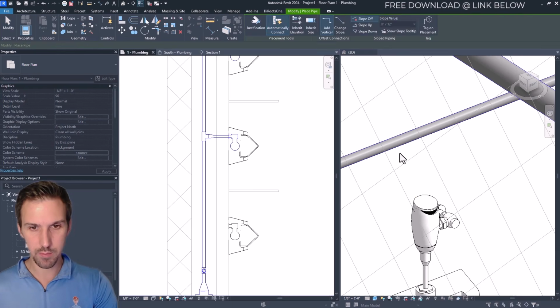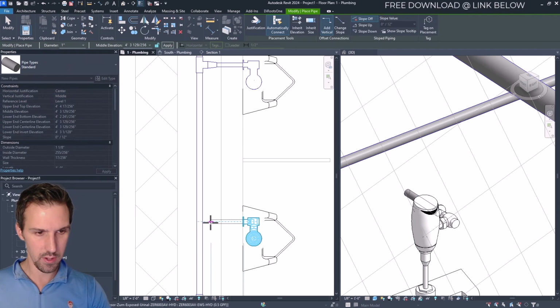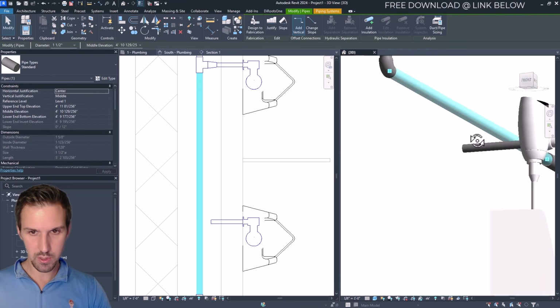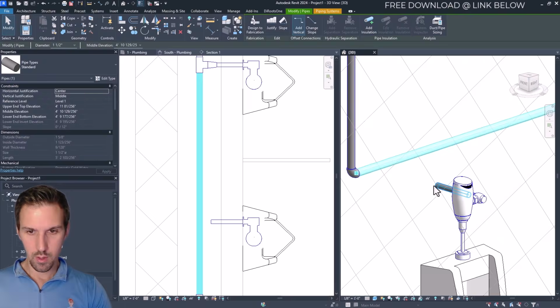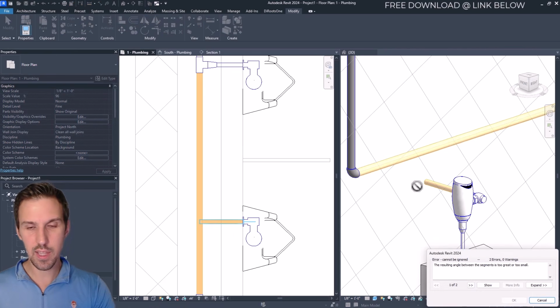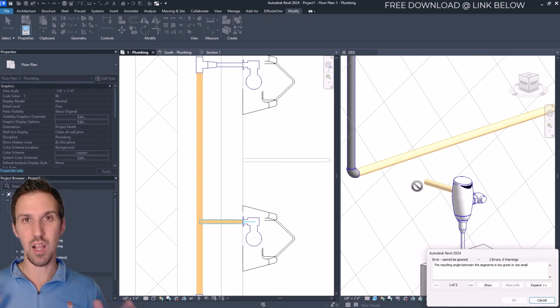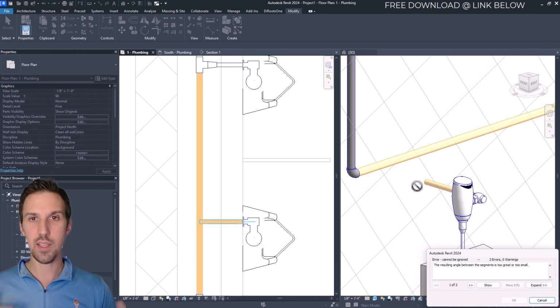All right, it didn't work. So this might not work. Let's try this again. So let's go to this point right here. And so what we need to do is make sure we have enough space to go down and over. To test this out, we can use the Trim Extend, and we're going to click where we want to go and click the pipe. And you'll notice that there's not enough space there to put the fittings, okay? So you're going to get this error a lot in Revit. Anytime Revit doesn't have enough room to make the connection, it's just not going to work.